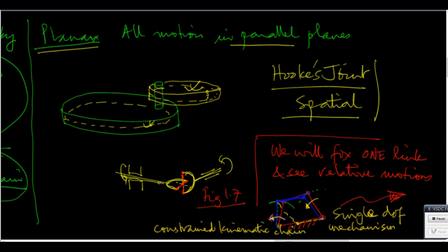Okay, good. We will do kinematic diagrams. Oh, by the way, if I had just 3, then it would not have any degrees of freedom. When I fix this, the whole thing is rigid. We need at least 4 links to have at least 1 degree of freedom. You will see later that it is possible to have more than 4 links and still have only 1 degree of freedom. That's not a big thing. So, for example, I can just show you right away.